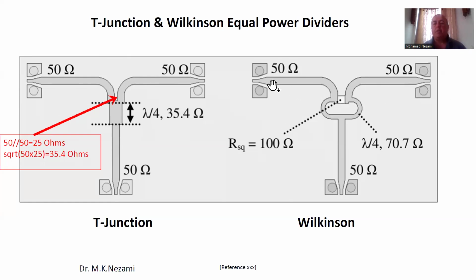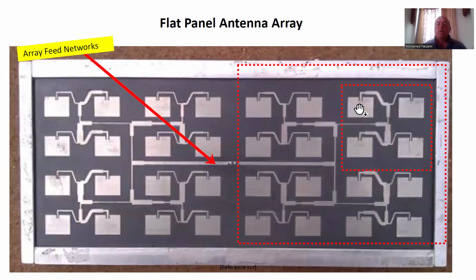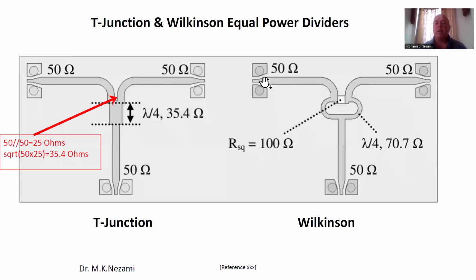While this is fully matched, if you look in here, it's fully matched whatever port you're in, and the two ports in here are isolated. So for antennas, if the signal in here was divided between these two antennas using an unequal Wilkinson split divider, whatever impedance this antenna sees, it's totally isolated from the other one. So the two terminals here have high isolation, which means this is good. Therefore, the pattern of the antenna and the mutual interference doesn't come into play, doesn't impact your system when you're using this. But of course, can you use this?